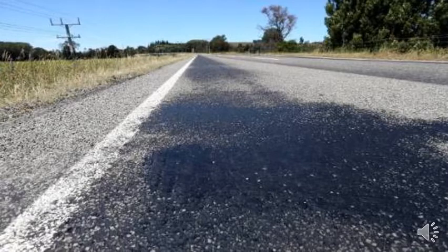So this is what happens. You've probably seen this on some of the roads in Kurdistan. In the height of summer, when the temperature gets really hot, basically the viscosity of the bitumen drops really low and it turns to a liquid, and basically all of the aggregate sinks to the bottom and you get these shiny areas on the road where the bitumen is just sticking to the surface. That's going to wash away as soon as it rains and as soon as car tires start wearing it away. And so that's a big problem.